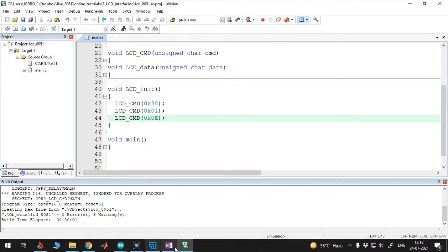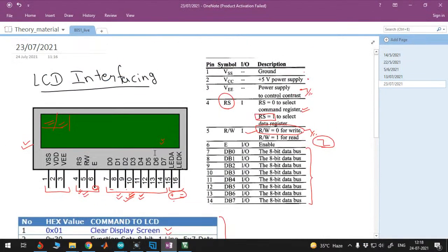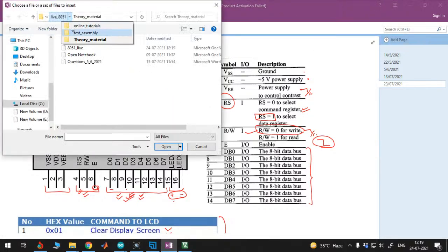Now there's one more thing in the lcd. When I'm saying 16x2, it means there are 16 columns and 2 rows. See, these are the 2 rows, and the address of this row starts from 0x80, and the address of this one is 0xc0, right? And then there are 16 columns there. So the address is 80, then 81, 82, and so on. It goes up to 8f. Similarly, the addresses of the other one.